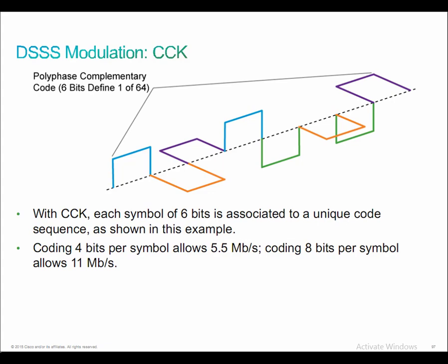To each 6-bit chip, 2 bits get added, which results in an 8-bit long code symbol. The 2 bits at the beginning are added to represent the orientation of the beginning of the symbol. So that's where they get the additional bits in this particular diagram. The remaining 6 bits represent the chipping sequence itself.